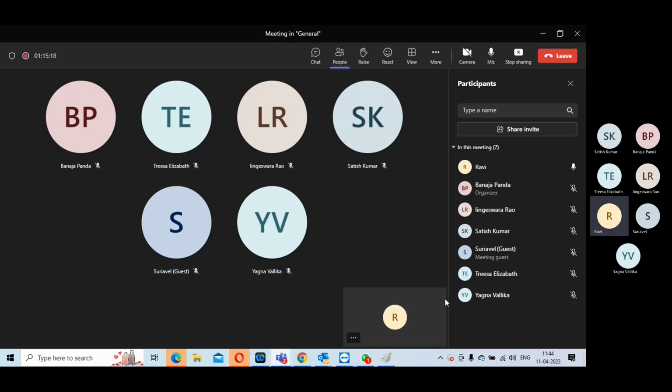It'll be there in the GDS also, but for PNR you use LEF. Initially you are not using GDS; for all the PNR you are using LEF. In the case of ICC, you are converting the LEF into Milky Way, with frame views, and that's the information you are using. In Innovus, you are directly using the LEF. In ICC, you are using the Milky Way, a converted version.